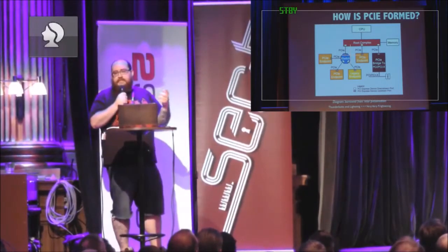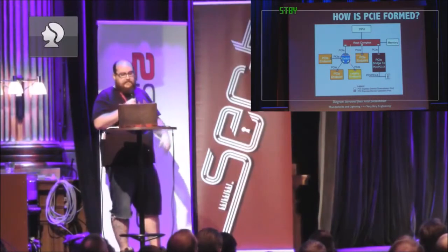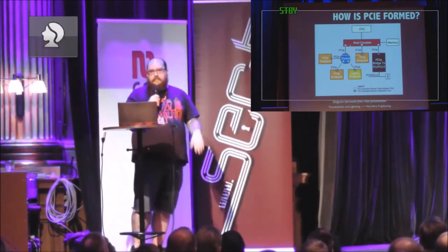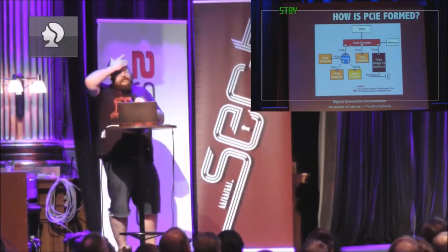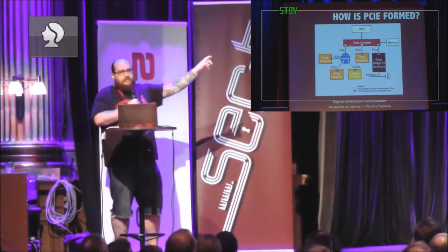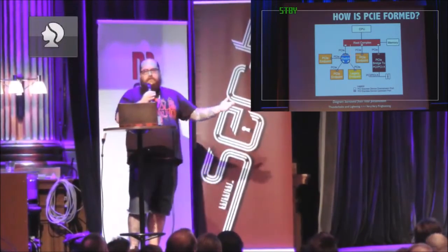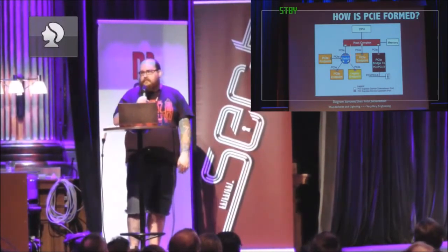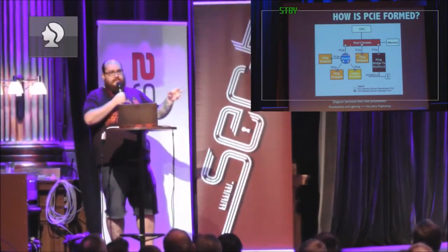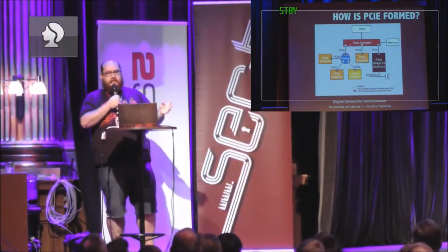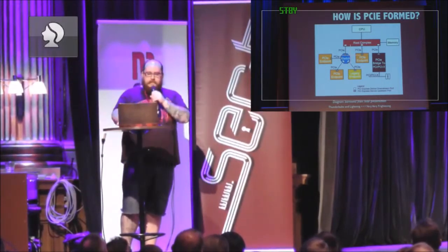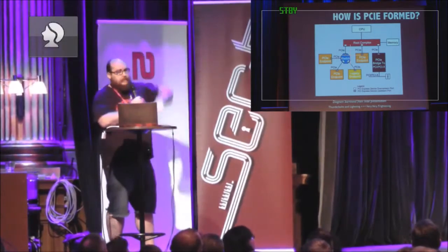And then off the PCIe switch, you might have a bunch of other devices. You can also have a legacy device that uses I/O reads and writes rather than DMA and message signal interrupts and all that kind of junk. You might also have a PCIe to PCI or PCIX bridge to connect real legacy devices. A typical desktop motherboard these days will have maybe one PCI or PCIX slot, then a whole bunch of PCIe 1-lane slots, maybe an 8-lane or a 4-lane and a 16, or maybe two 16s if it's a super gamer nerd system. And then, importantly, you've got the memory also connected to the root complex there.